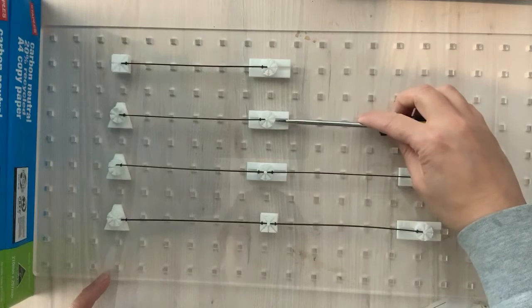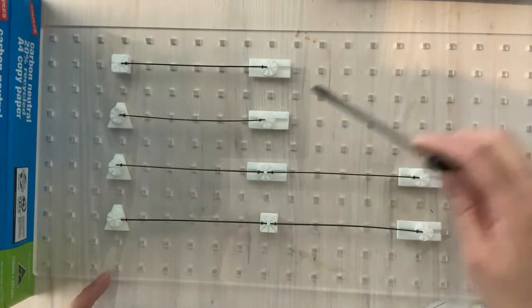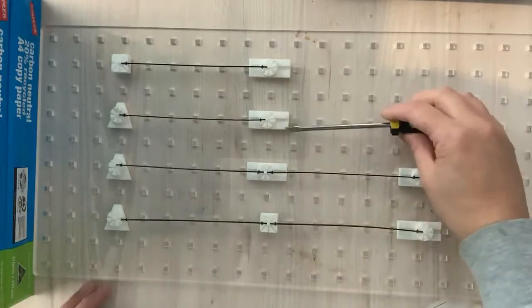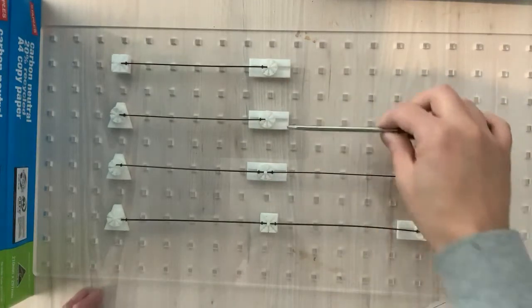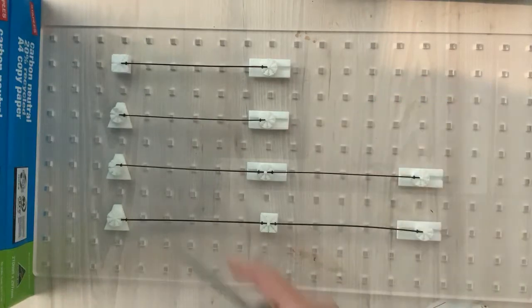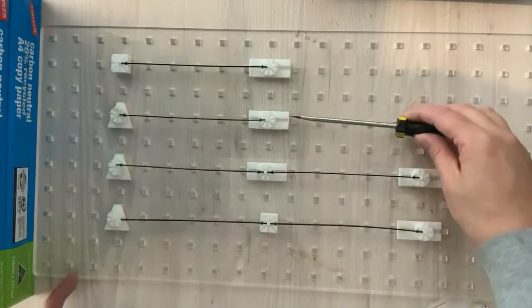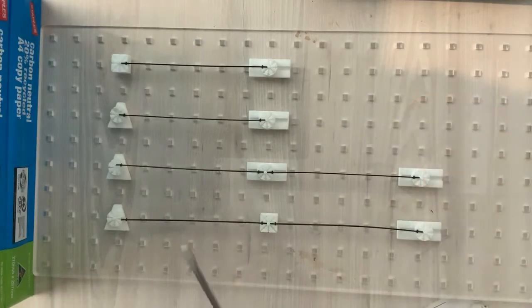When that load reaches pi squared EI over L squared, suddenly everything goes off to infinity. Remember, here I'm actually applying a displacement, I'm not applying a force. If I was applying a force, as soon as it reaches the buckle load, everything would shoot off to infinity: deflections, stresses, everything. So a beam or a beam column or a column cannot take an axial force more than pi squared EI over L squared. It's theoretically impossible.